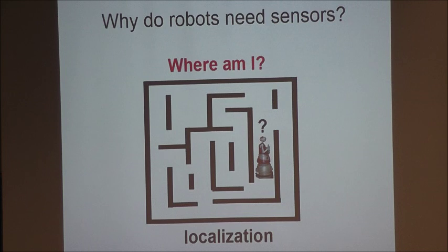So as you know already, the mobile robot needs to know where it is. So where am I? You need to be able to locate yourself. Okay. And last time we mentioned that with the help of landmarks around you, fixtures around you, and estimation theories like Kalman filtering, you can actually try to minimize what we call the odometry error, where you should be and where you actually are. Okay, there is always a discrepancy there.